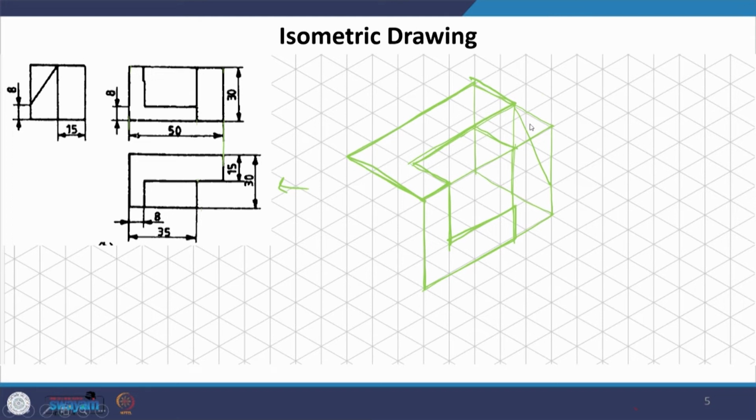Now, in the side and front elevation and the top, there is no line in the top view which is coming here, which means that there is nothing here. But then we also get to see that there is an inclined line, which implies that there is something. But if we were to have an inclined line here, we would be able to see it in the top. So, what it implies is that this edge is probably here. We will see it from the side, which is what we are seeing here, but we will not see it in the top. So, if I remove this, this is what we are going to get.